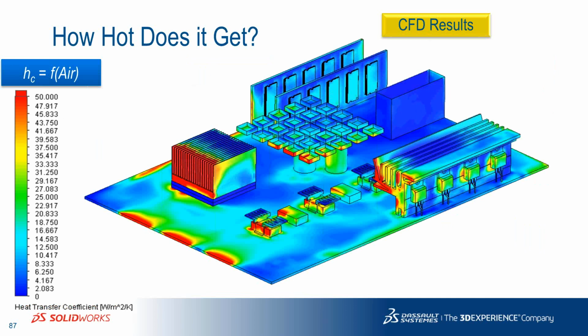Now, like I said before, flow simulation actually calculates the convective heat transfer, and you can actually get a nice distribution of the convective heat transfer everywhere on the design, the geometry. And you can clearly see, for example, on the heat sink, the convective heat transfer is not uniform or constant. It's a lot of red on the front end versus the back end is blue. So it tells us that the convective coefficient is all over the place, anywhere from 0 all the way to 50.